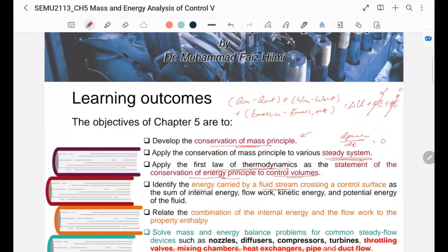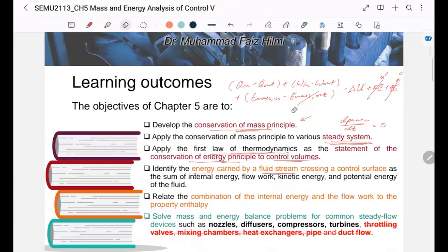And in a closed system, the energy due to the mass exchange is also 0 because in a closed system, there's no mass exchange. But in today's open system, this will not be 0. So we need to know how to define the energy of mass. Sorry, the energy carried by the mass of the fluid itself. So that's what it means by the energy carried by the fluid.